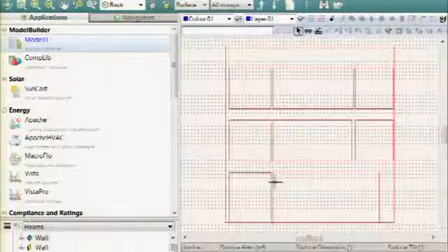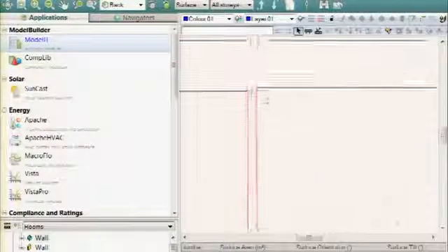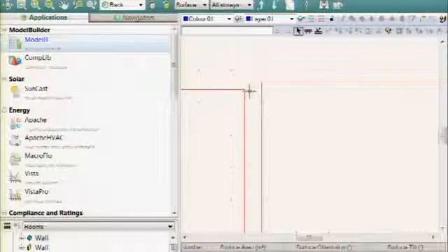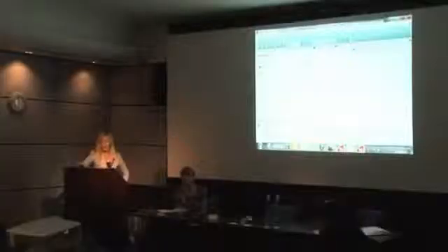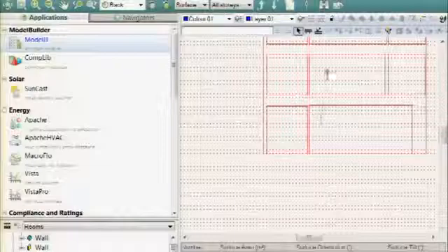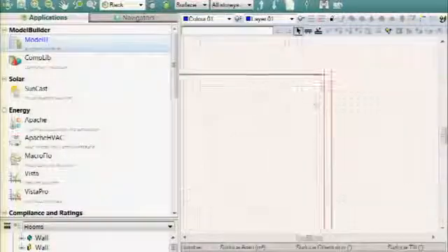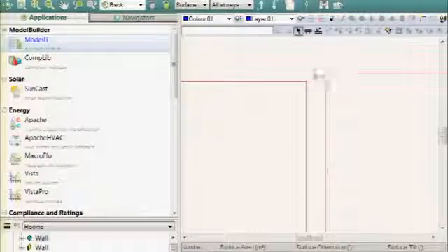And I think every case is going to be specific to really your decision as well. Like in MacroFlo, is this type of difference in window opening going to cause a lot of errors to your calculation in the overall building? Depending on whether it is openable or not, because some panes are openable, some panes are not. Right. So if this was an operable window, and all of these were operable windows, will the differentiation in this from that affect your building? And you probably know better than I do as engineers.